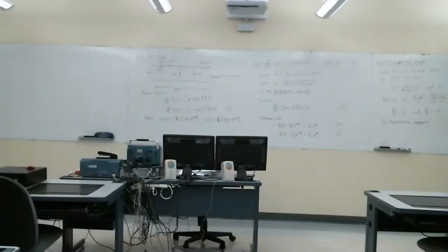But if you notice, and this is typical, our j omega L term is much larger than the R term, and the j omega C term is much larger than the G term. So if we neglect the R and the G, then the j omegas cancel out.